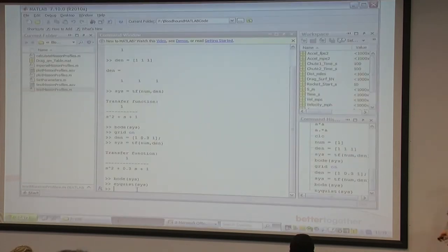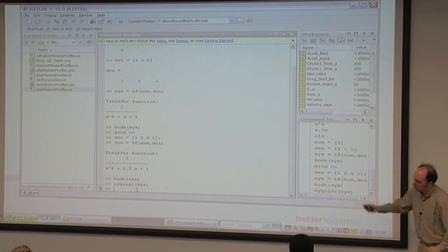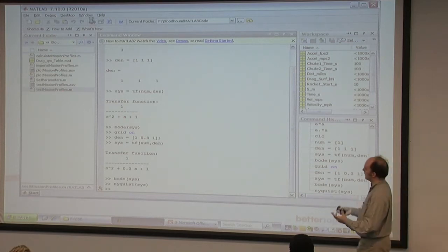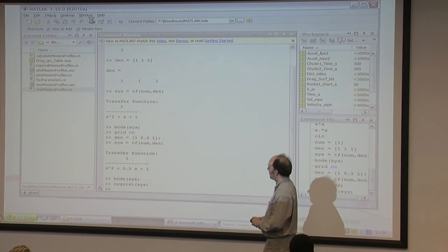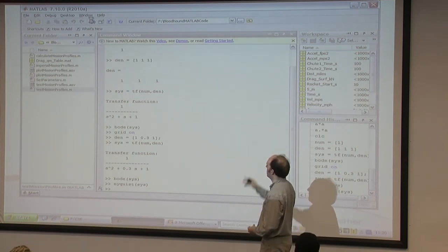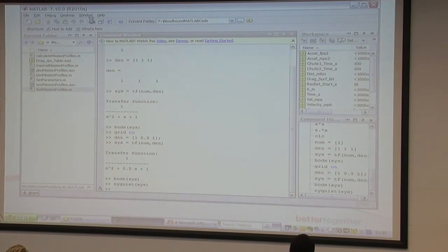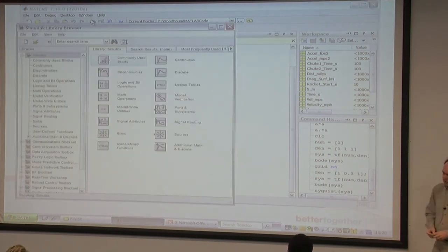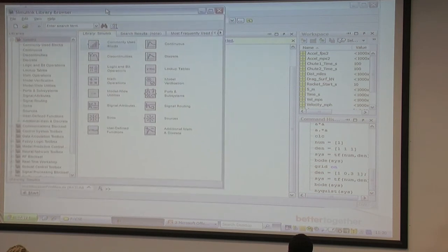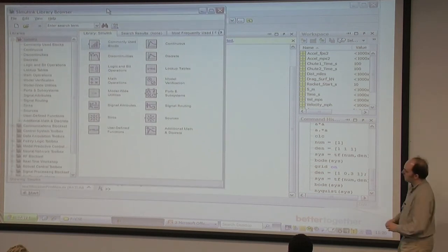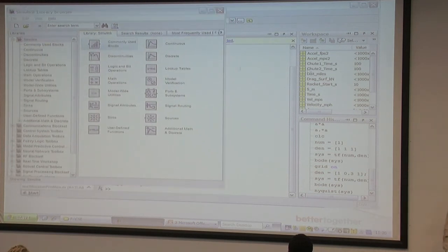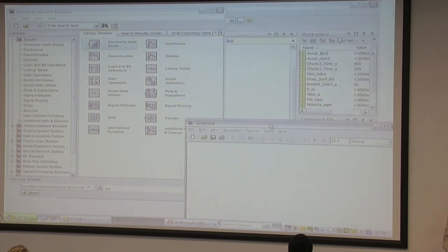To get to Simulink, you see the button up there, the colours. Okay, that's Simulink. You click on it, and it opens Simulink, which is, like I said, a different set of tools, a part of MATLAB. You don't use the command window in the same way. Okay, so it takes a little while. It's just booting up. Okay. So here's our library, and I'll make a new file using the new button. Okay, there's my new Simulink window.